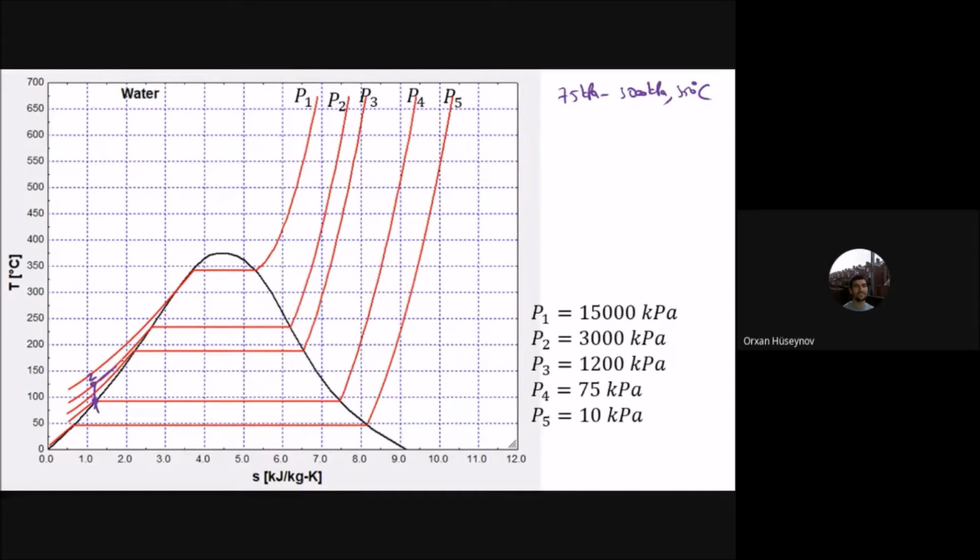This is isentropic, and then you will have the boiler. This part is the boiler part. The boiler is at constant pressure. This is a heat exchanger, and heat exchangers are at constant pressure, and it raises the temperature to 350 degrees. This one is point 3. The boiler and condenser are heat exchangers, and heat exchangers are at constant pressure. Then from 3 to 4 you have the turbine, which also goes in an isentropic manner. So the turbine will be in that way, and you have the 4. This is the process direction that you are going to have.